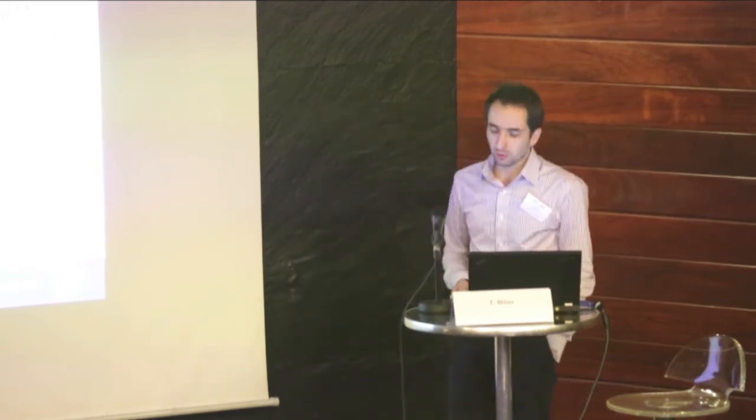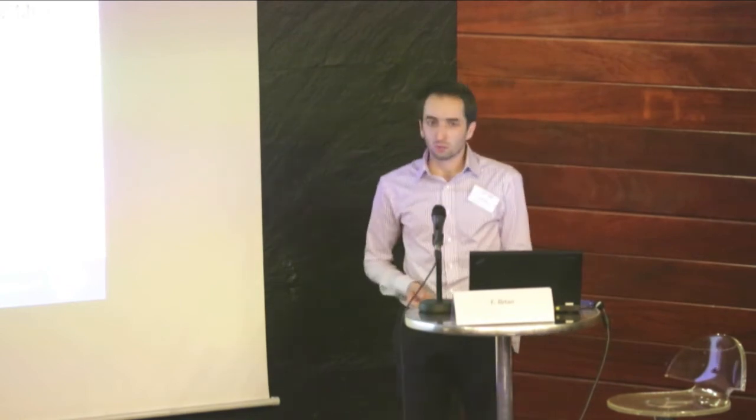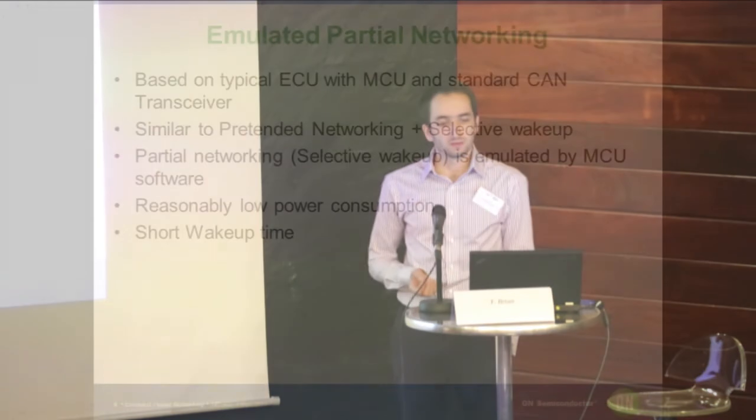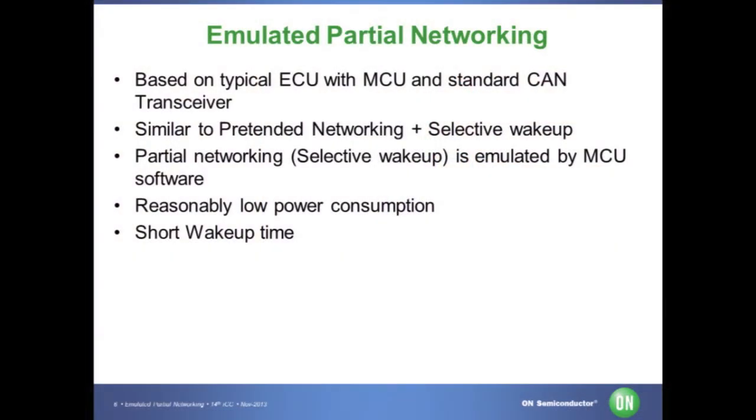So now the emulated partial networking. What we tried was to combine the advantages of both partial and pretended networking, and integrate the selected wake-up functionality without having the special CAN transceiver. So just with a standard CAN transceiver plus the microcontroller.